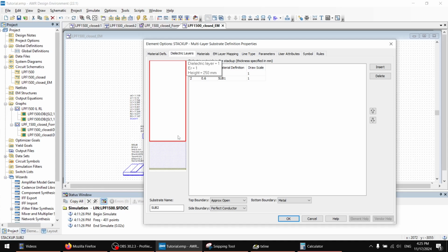In more advanced options, you can also add, for example, a metal cover above your circuit, because at higher frequencies, if you add some metal above your circuit, depending on the height, it will also affect your tuning. That's why you might want to put some absorbers and so on to avoid the reflection from those covers. But we will assume that our PCB is just laying on our bench. We don't put hands close to it, and everything is free air.